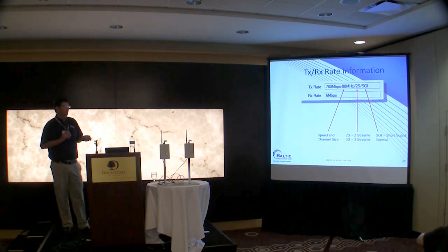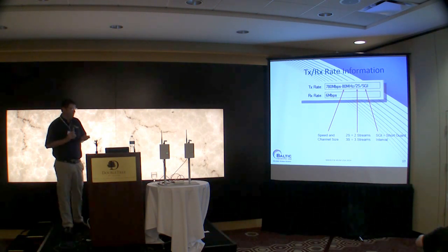So if it says SGI, that means we're operating in short guard interval. That's the most optimal configuration. But you may not see an SGI at all. If that's the case, we're in a standard long guard interval. And in long guard interval, you're not going to see a top 866. It's going to be a little bit lower than 866.